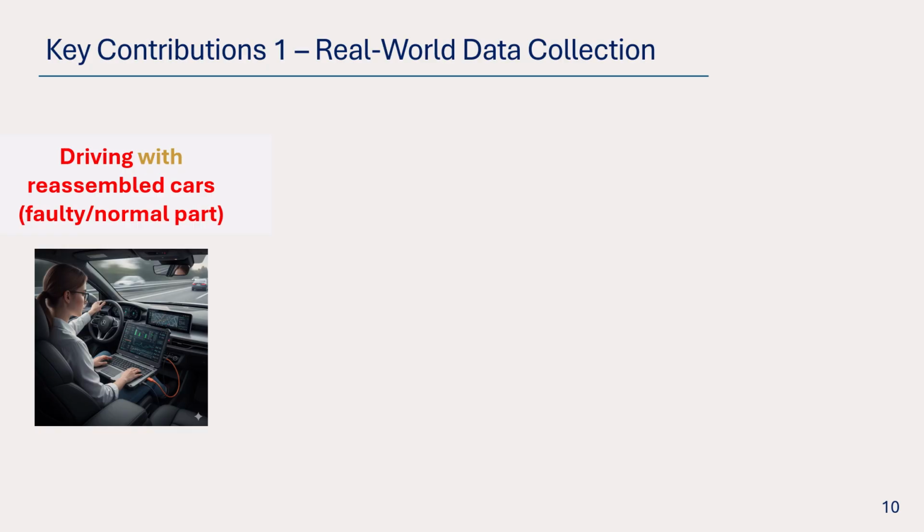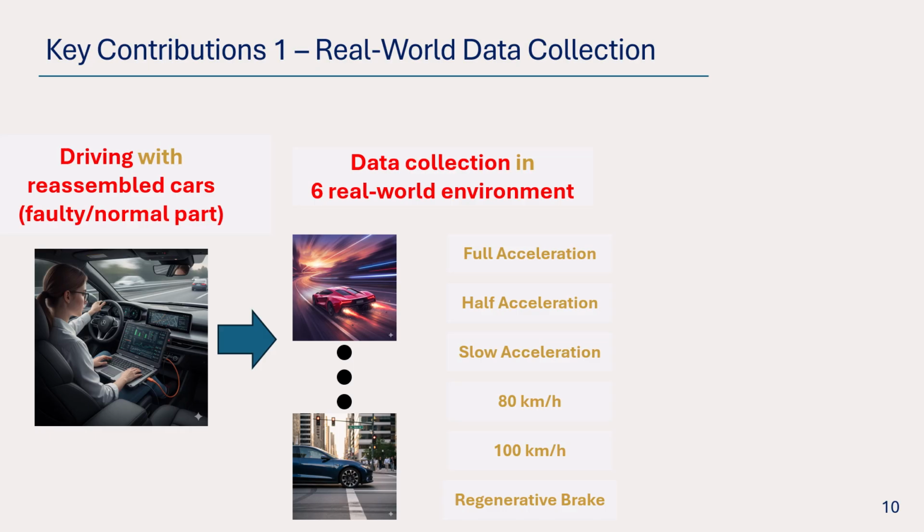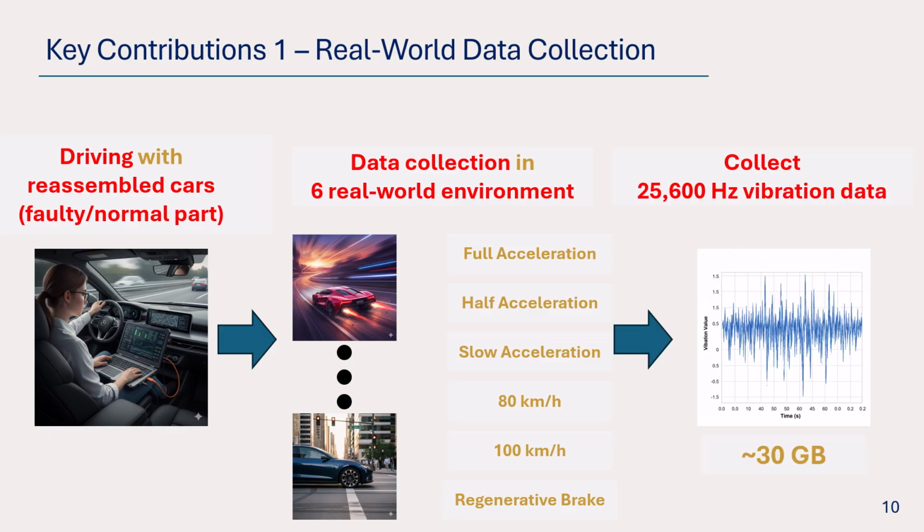After that, we test drove the sensor-equipped vehicles ourselves, collecting data across 6 real-world scenarios, from full acceleration to steady cruising and braking. Through this, we were able to acquire 13 gigabytes of high-frequency data at 25 kHz.